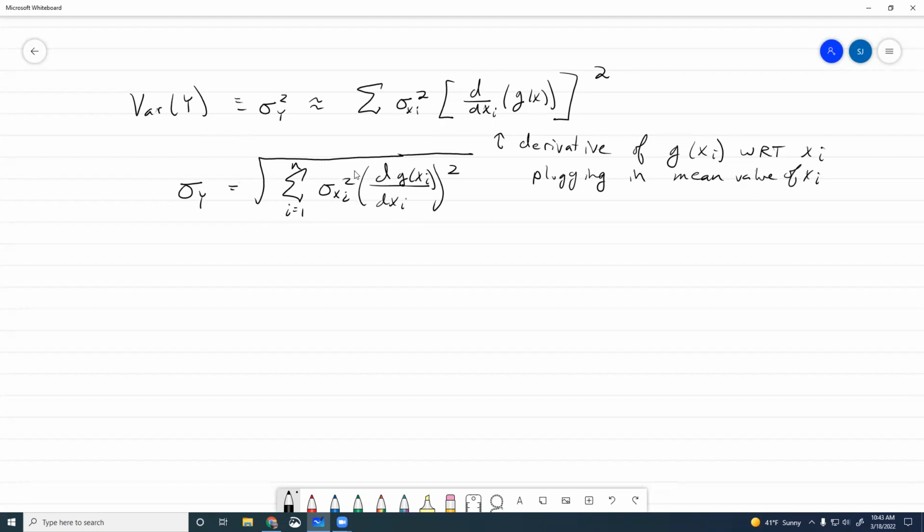And then just an example of this would be, say we have, someone give me an equation. We're going to do impromptu. This always goes well. Bernoulli's equation. Okay, so we have the head loss is equal to P over gamma plus V squared over 2g plus Z. So this is for head loss in pipe flow. This is not really, oh, sorry, this is just the energy. Let's do energy, just say H.